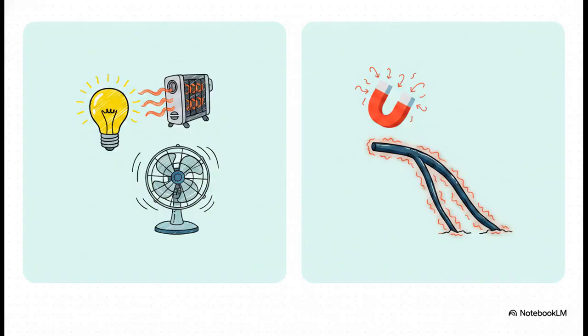Ultimately, the contrast here is pretty wild. While active power is out there doing all the heavy lifting for society, this oscillating reactive power is just acting like a massive bottleneck for the entire infrastructure. It does zero physical work, yet it takes up precious capacity on the transmission lines. And even worse, as it sloshes back and forth across the country, it physically heats up the transmission wires, causing real energy loss, and creates frustrating voltage drops that can literally cause brownouts for the end user.